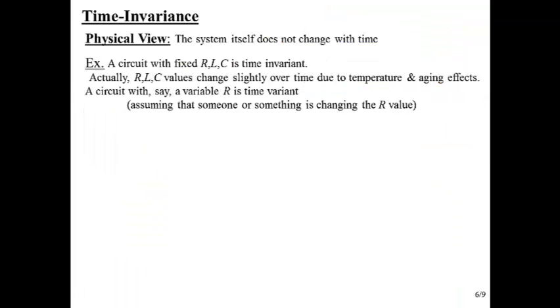The third property, we've had causality, we've had linearity. Third property is called time invariance. And basically this just means that the structure of your system, how it behaves, how it works, its inner workings, aren't changing over time. So you've got some RLC circuit. The resistor value, inductance value, capacitance value is fixed. They are not varying with time. Their values are time invariant. Then the system itself is time invariant.